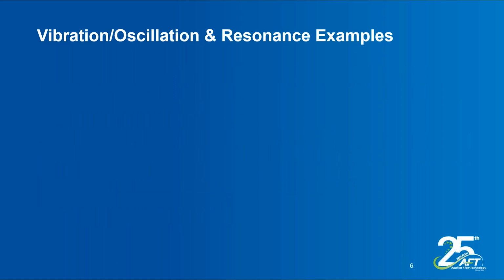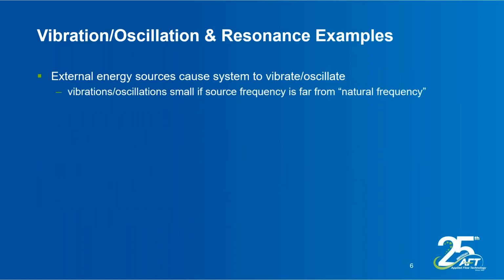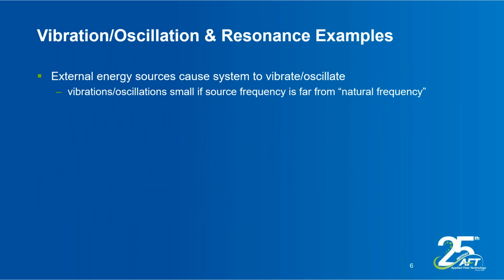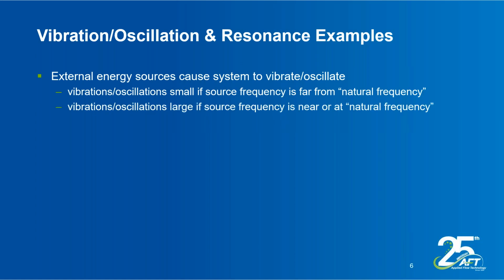So I wanted to include some examples of vibration here, and I've got a couple of videos that are useful. One note that I want to point out is if you have vibrations that are not at the resonant frequencies, those will typically be small and they may not be problematic, but they certainly can be if your vibrations are at or close to the natural frequencies, and that's where your system will start resonating.